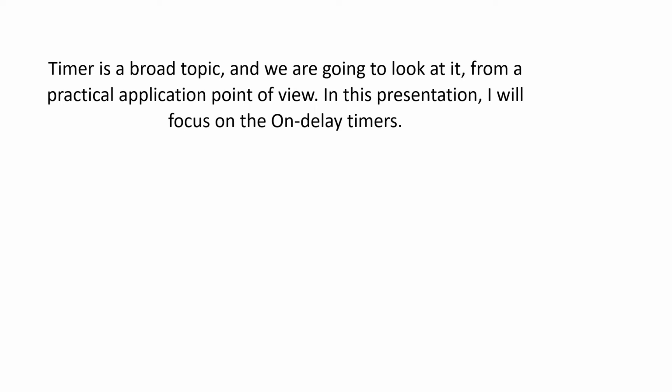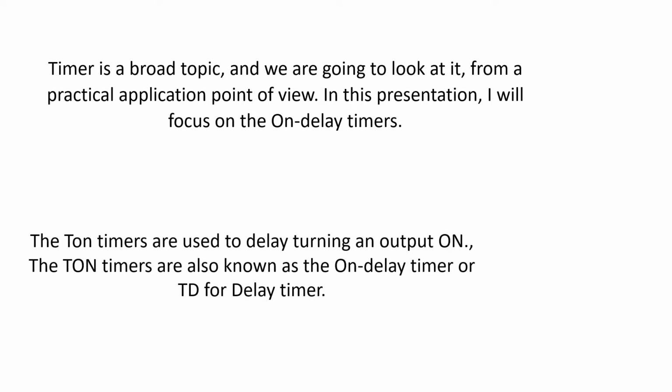Timer is a very broad topic, and we are going to look at it from a practical point of view. We're not going to look at it from an academic point of view. We're going to look at it in a basic application in automation and controls, in constructing electrical control panels. Timer can be very complex because it's a very vast topic. So we're going to focus on the delay timer. Turn-on timers are used to delay turning an output on. Turn-on timers are known as the on-delay timers, or TD for delay timer.